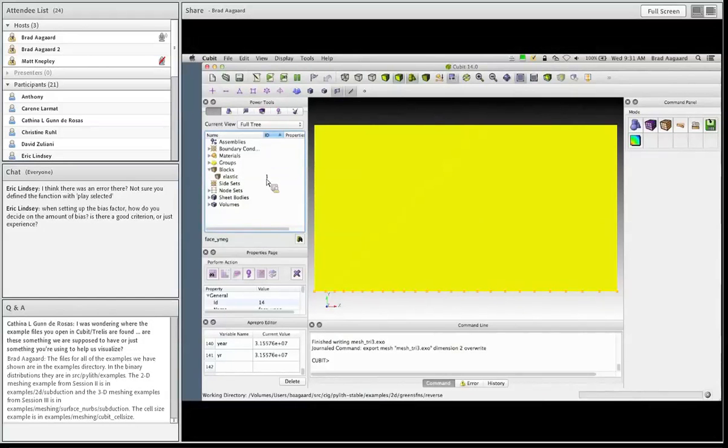And so, in this particular example, we have the fault intersecting the edge. Everything else is essentially, we don't have much of a spatial dimension, and so in this case, if I was trying to resolve something like that size, I wouldn't let my bias factor be so large that my discretization size was getting bigger than my geometric features.